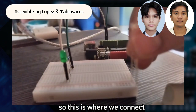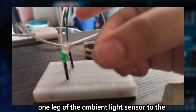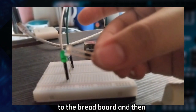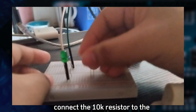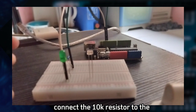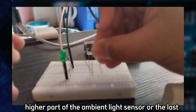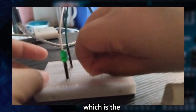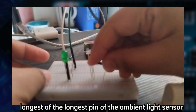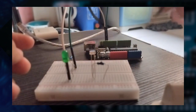So this is where we connect one leg of the ambient light sensor to the breadboard, and then connect the 10K resistor to the higher part of the ambient light sensor, or the plus, which is the longest pin of the ambient light sensor.